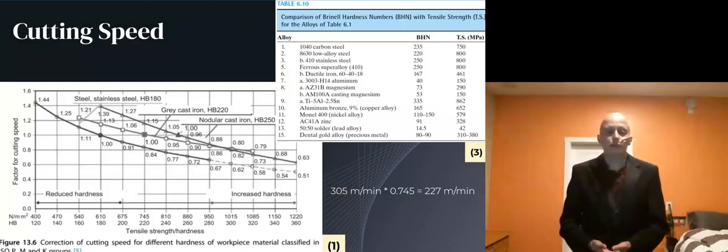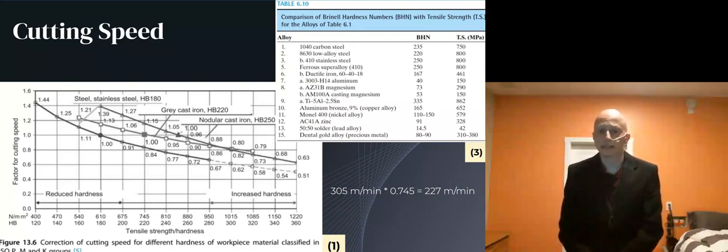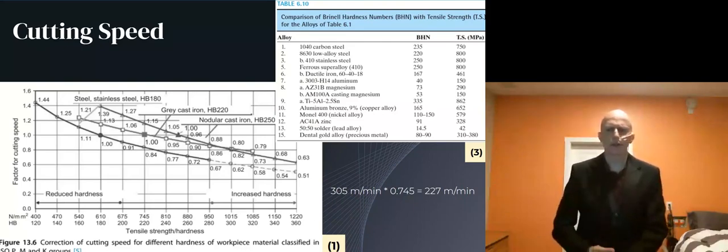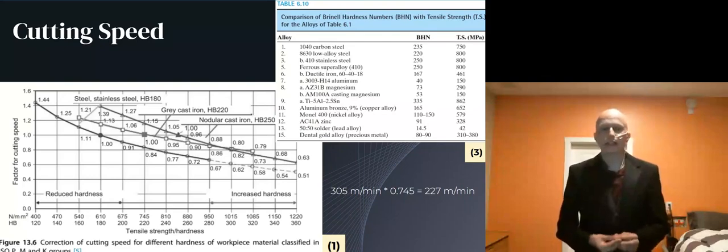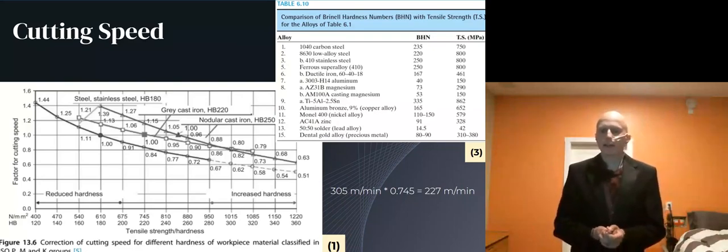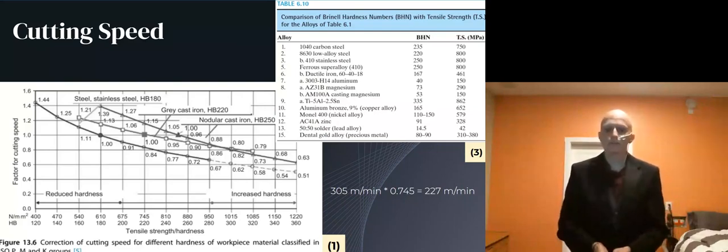As you can assume, tensile strength and hardness have a large impact on whether a carbide drill bit can successfully cut through a given material. As a reminder, hardness is the resistance of a material to indentation, and tensile strength is the resistance to it breaking under tension. Well, machinists have collected data for each ISO material subgroup and determined an initial cutting speed based on these values.